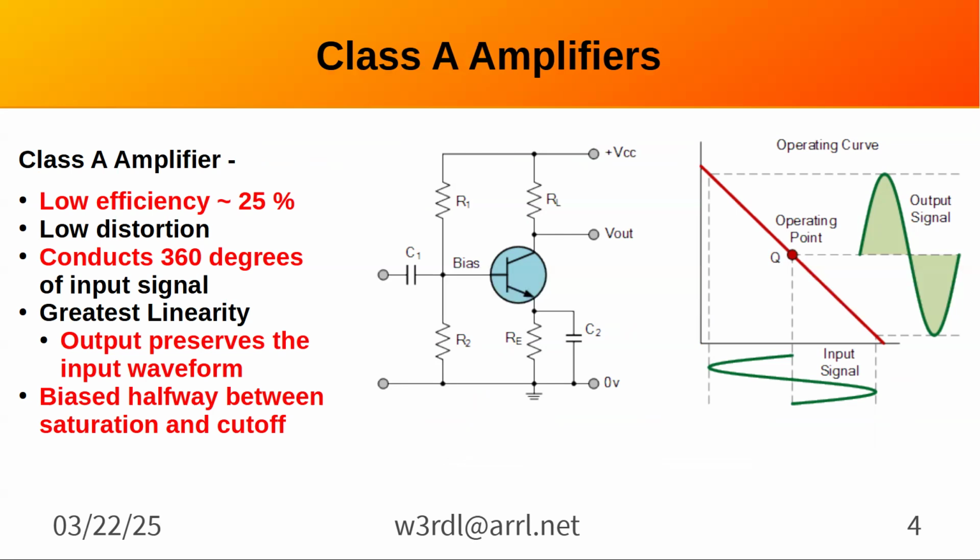So it gives you some nonlinearity in the amplification, usually compressing the positive peak more than the negative. And if you go to a push-pull arrangement, that was one of the reasons to do that, because then you get that effect on both halves. So it's closer to being linear.